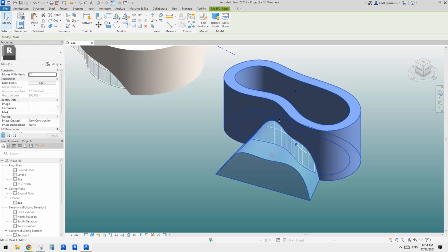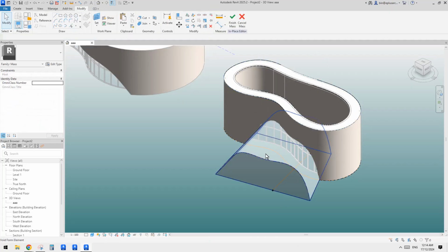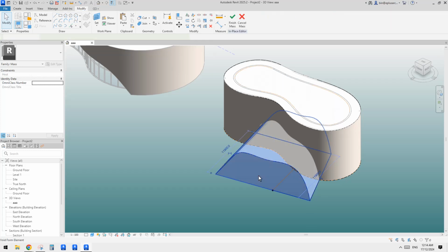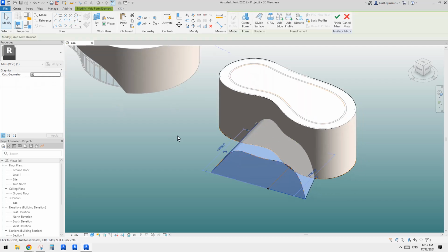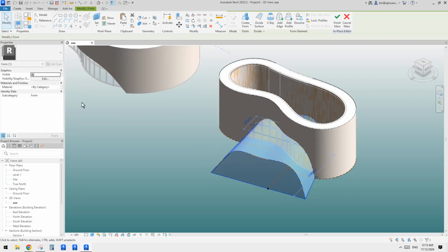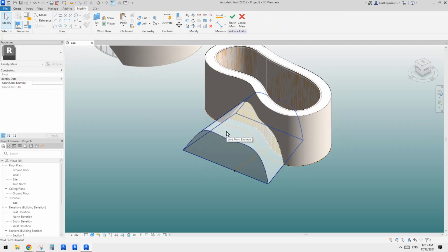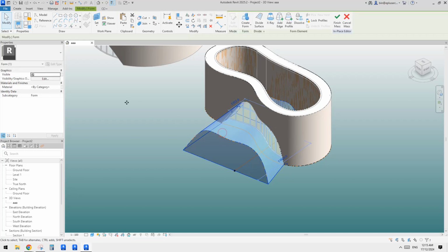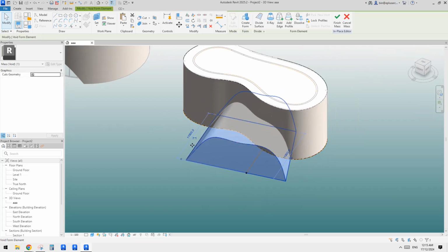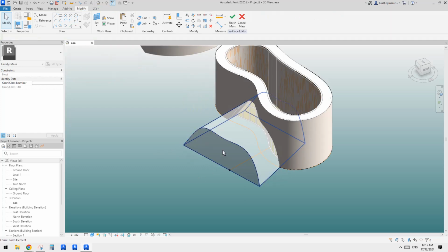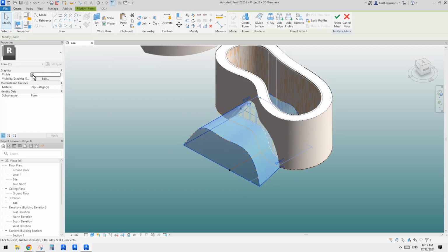And then you probably want to hide this. You can go to the mask, and then, hang on. Oh, we can't make it invisible. I saw that we can just untick a box, but it looks like we have some issue. It looks like you need to pick the right one. So you need to tab once and click. If you directly pick this one, it won't let you. Okay, great. Tab select. So you have the option to uncheck this box and finish mask.